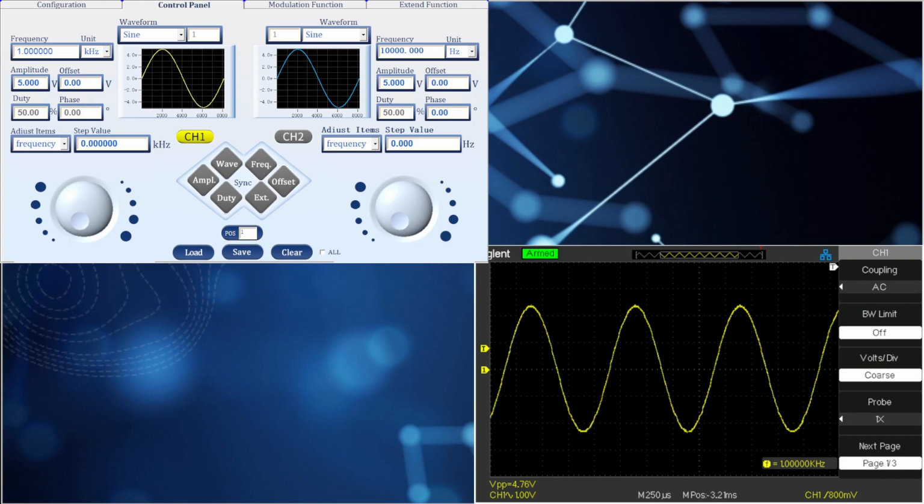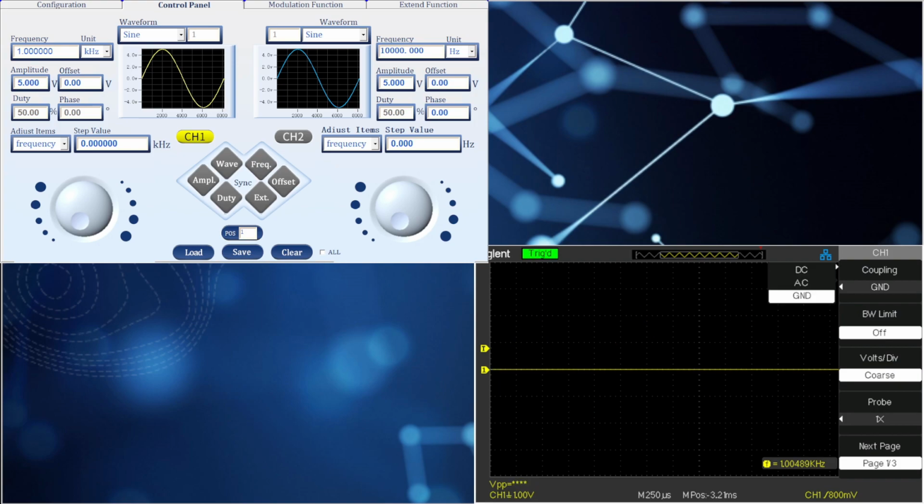And then over on my oscope, if you recall from where I taught how to use one, I'm going to ensure that I first couple to the ground and set my reference where the X and Y axes meet at their absolute 0 point. Then I'll change my coupling back to AC.